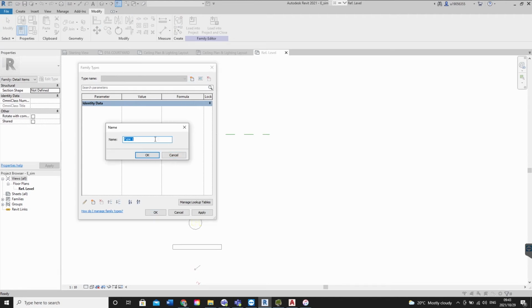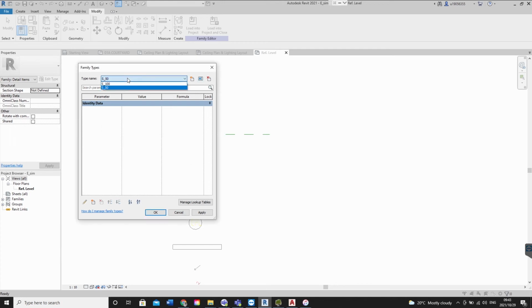Okay, so here we're going to 100, so you can just go capital S underscore 100. New, S underscore 50. Sorry, I should have put an underscore. I didn't do that. There we go. Okay, so you understand that's scale 100, scale S50.